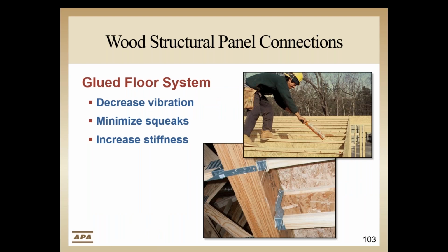Adhesives are often used in addition to fasteners to bond wood subfloor to joist assemblies. This adhesive helps eliminate floor squeaks, and the bond creates some composite action between the joist and subfloor that increases the stiffness of the floor system. You can consult APA's Design Construction Guide, Residential and Commercial, for additional details and a description of the APA glued floor system.